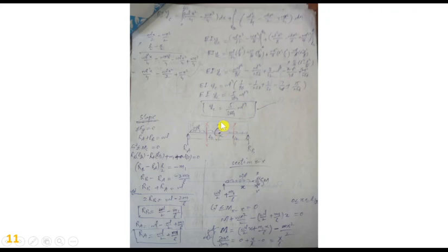If that is the case, you will apply a fictitious moment M1. So when you apply here, it will have effect in reactions RA and RB. You will find that and then take the section xx. This is the value of M for section xx. Here M1 is involved, so you will take the derivative with respect to this fictitious moment, because now we are doing for slope, and partial derivative with respect to fictitious moment, and this value is this.